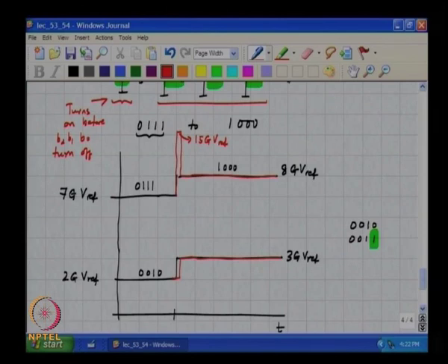Number of transitions. Pardon? Number of transitions. One thing is that nothing is switching off, only current sources are getting more and more added. Correct. Whereas in the previous case, 3 of them are switching off and 1 of them is turning on. That's correct. If there is a time delta t difference between how fast you can turn on and how fast you can turn off, then you will see the kind of spikes you saw. Whereas even if there is such a timing skew in the second case, you will not see any kind of spike like that.